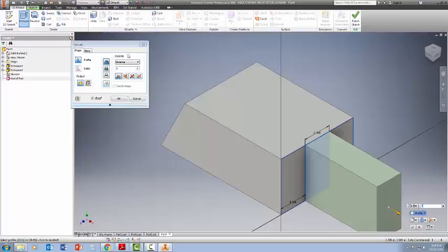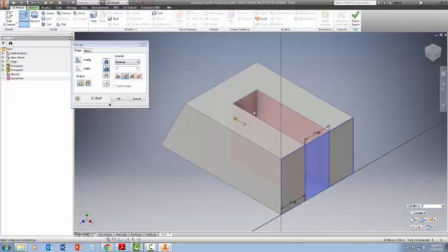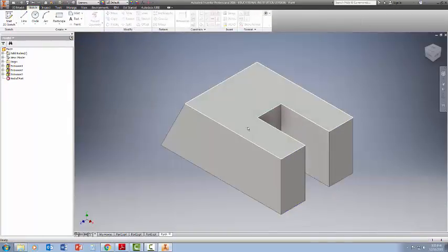I can either type it in here, or at the bottom right I can type it in down here. It doesn't make a difference. I can also change the direction, either here or down here. So in this case, I'll just for laughs, I'll do it down here. Okay, direction 1. So I'll go down to direction 2, and look, it's going in 3 inches. I don't want it to go 3 inches, I just want it to go in 2 inches. So I'm going to delete the 3, put in a 2, it makes the change on here, hit enter,